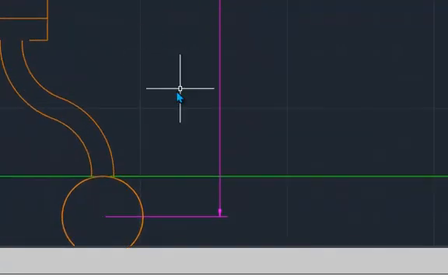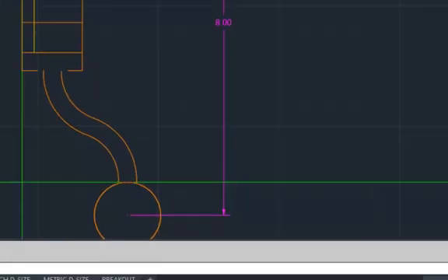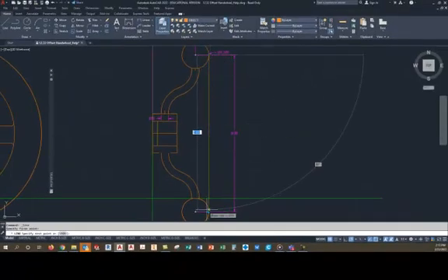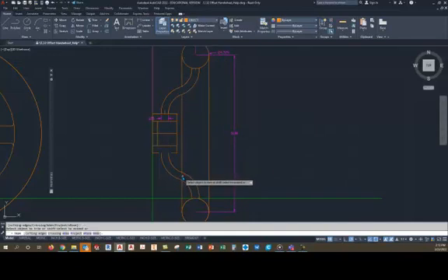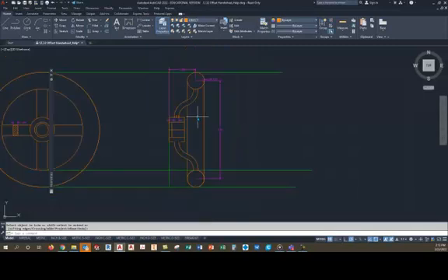Now the other thing is you got to remember that there's a line here and there's a line here because it's a continuous wheel, and therefore we would need to trim these pieces out like so, and there'd be a hidden line right there and a hidden line right there. Maybe something else that you might not have thought of, but that actually looks pretty good.